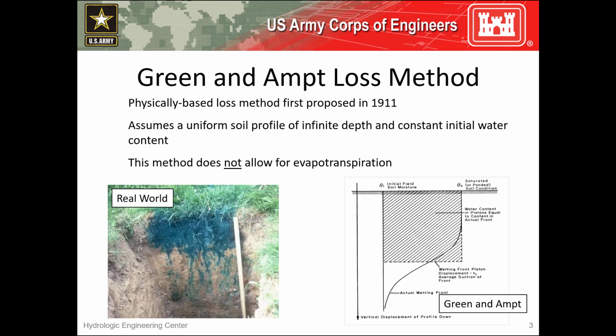The Green-Ampt infiltration equation is more physically based than the previously discussed options. This method was first proposed in 1911 by two guys named Green and Ampt, as the name implies. I'll spare you the gory mathematical details, but within this method, infiltration proceeds with so-called piston displacement, as shown in the figure in the bottom right.